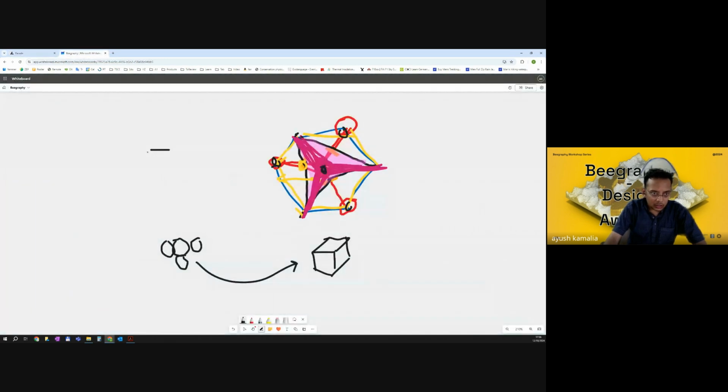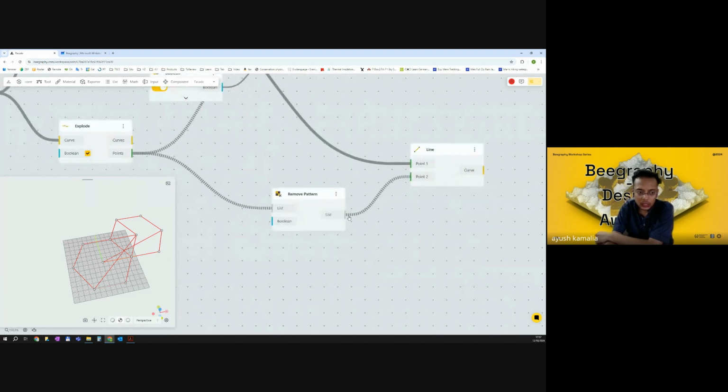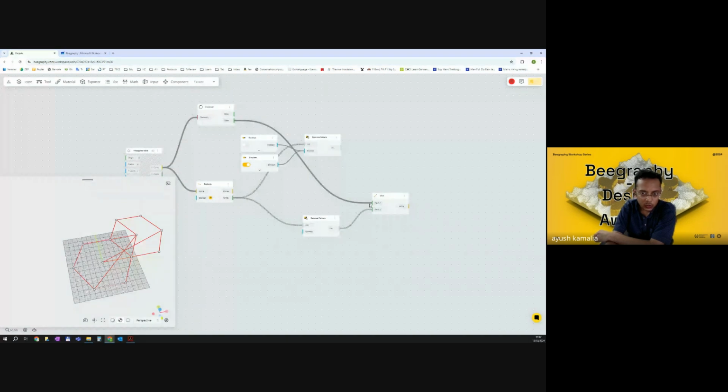What we wanted is a hexagon like this, and from the center point, there should be 3 lines, but we get something funny. It's because this is the line which shows there are multiple lists going on as an input. So it's a tree. But in this input, it is only a single list. So the center points of the different hexagons are not corresponding to the relevant points on the edge of the hexagon.